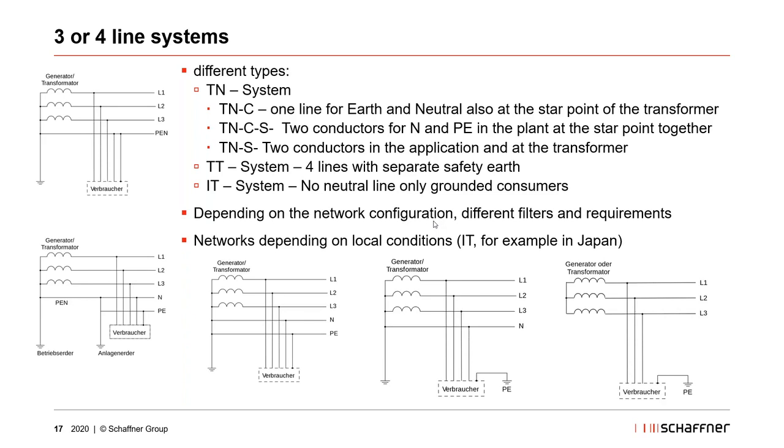The IT, the insulated transformer, for example, we have the IT grid network filters, which have a slightly different setup of the resistors. The discharge resistors to Y, to protective earth, need to be a little bit higher than others, because without this we are not able to do insulation measurement in this IT grid network.